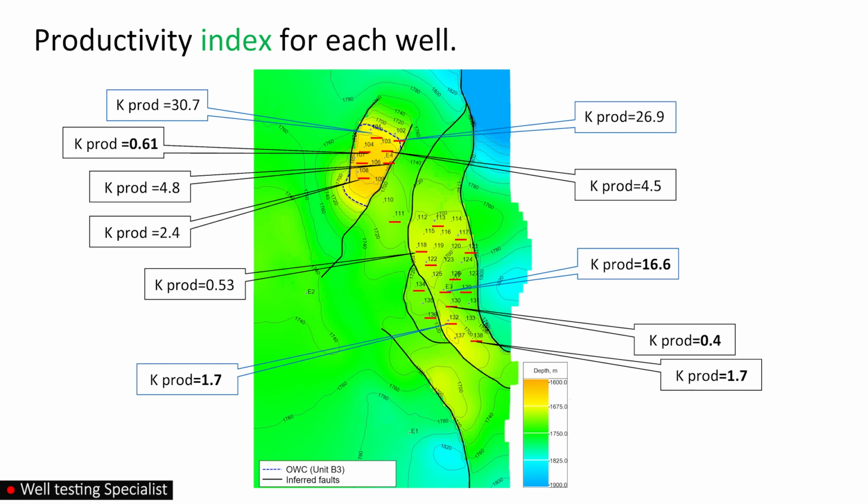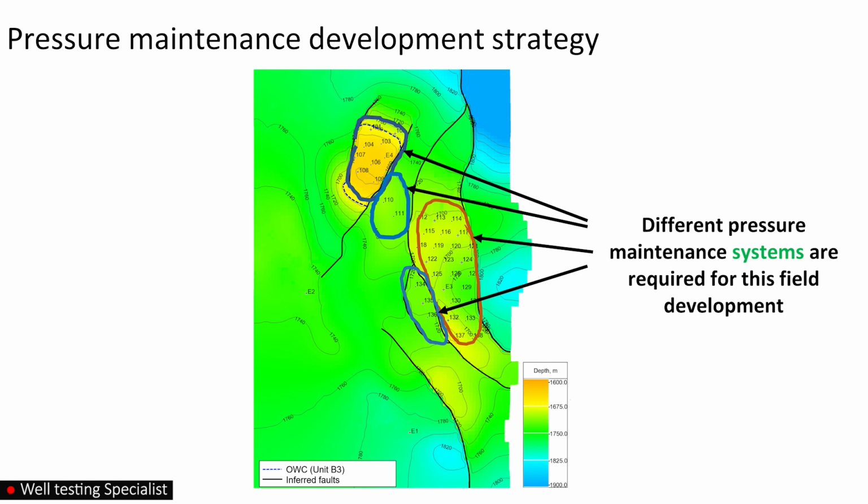There are wells that have very low productivity. These wells should be considered for recompletion, put on injection, or stimulated to remove formation damage or the high skin. These wells include 104, 130, and 118. As mentioned above, all faults are sealing faults and non-conductive. Therefore, I recommend to develop this field on a closer spacing, provide effective pressure support, and remove formation damage.